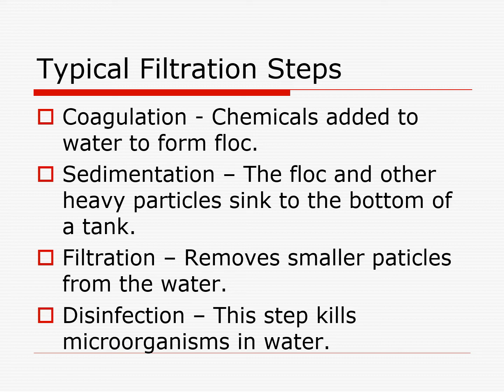Once I have the heavier objects out of the water, then I go through my filtration stage, where I remove the smaller particles from the water. The last step in a typical filtration plant is disinfection, and that step is there to kill microorganisms in the water.